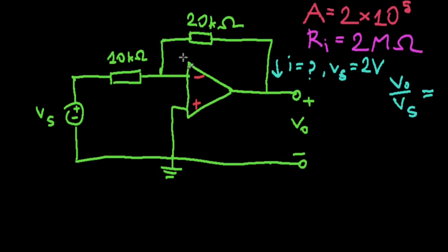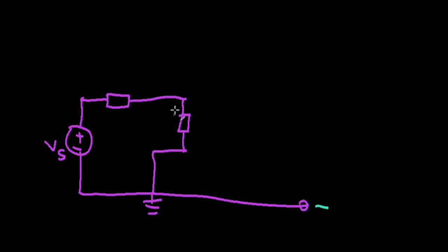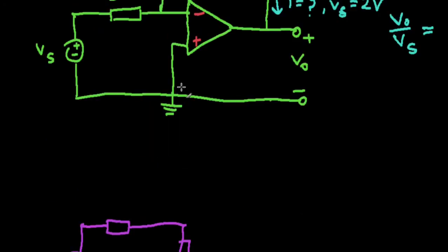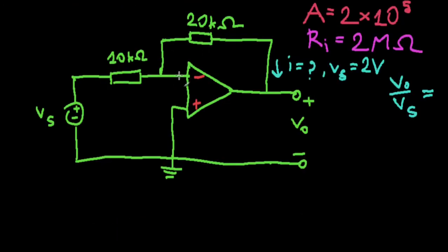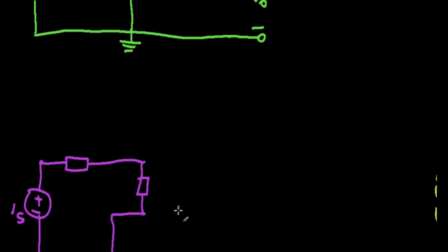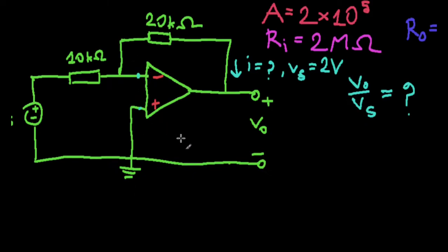As you can see, we just replaced the op amp. This is going to have two parts to it. These were my input terminals. All I did, as we saw in the diagram, was put the equivalent circuit: from this end it's just your input resistance, this large resistance connected to your two inputs. I just put that resistance between those two input terminals.